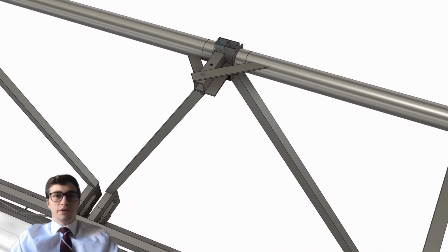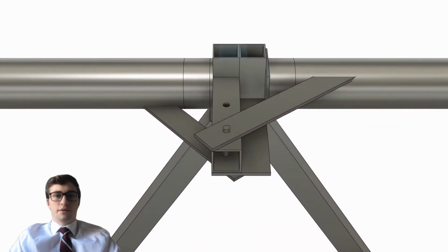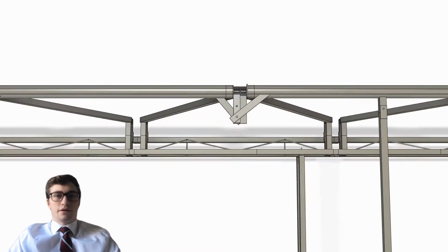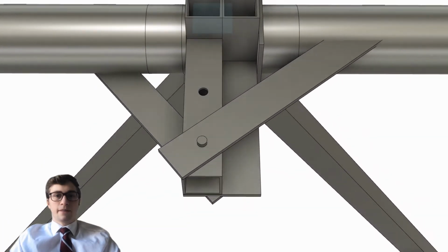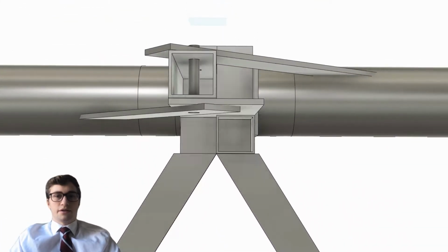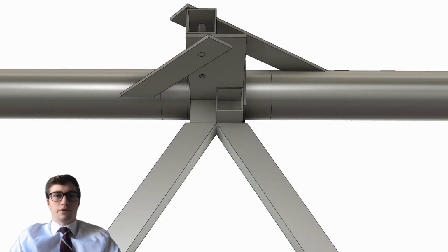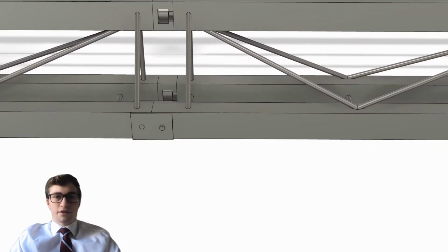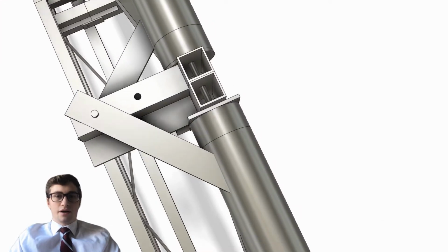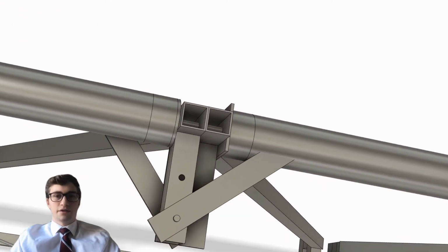The connection between the upper cord members utilizes plate and inner tubing to bring together both round and square tube. There is already a pre-welded peg incorporated into this connection. The main strength of this connection is that it connects 4 members with only a single bolt. So as you can see, this bridge is also advantageous because these innovative connections allow for an easier construction experience for all builders.